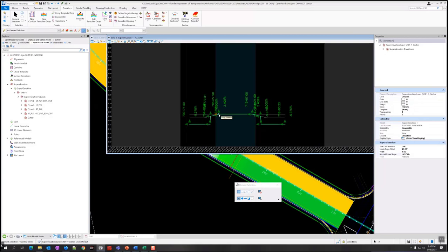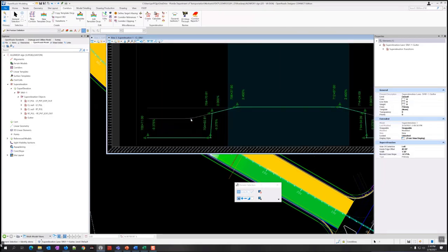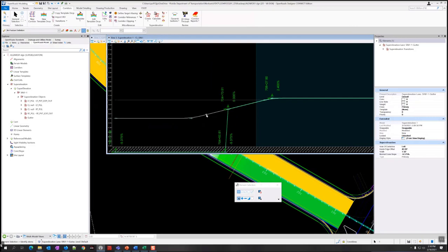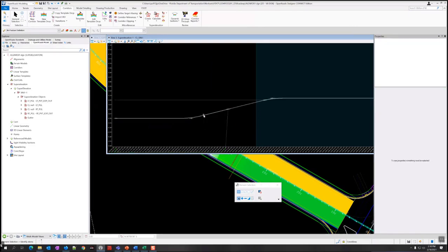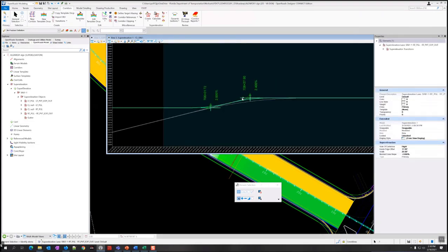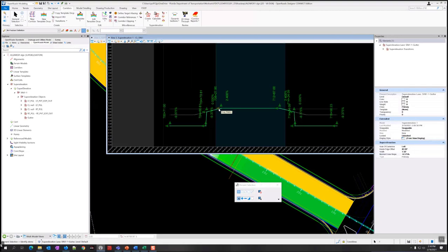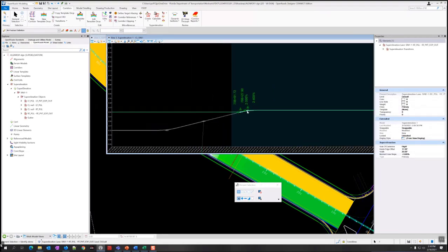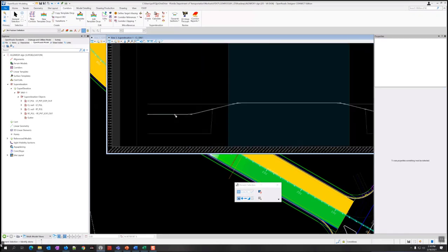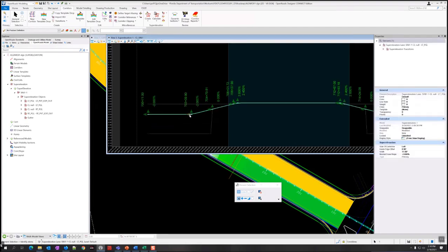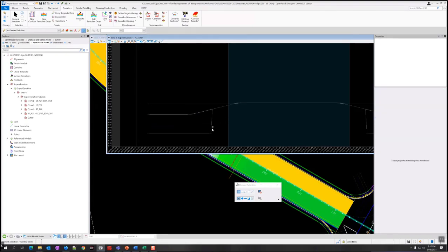If you have these constrained in some way, there are options in the super elevation editor that can constrain them. Then you may not have handles on all the points, but because we imported it, it doesn't import any constraints. So there are no constraints. If you open this on a new one that was just calculated, it may be fully constrained. So you'll only have the option to edit one of the profiles, and everything else will follow. So you can certainly play with that if you want to do it visually. That's another option for you.